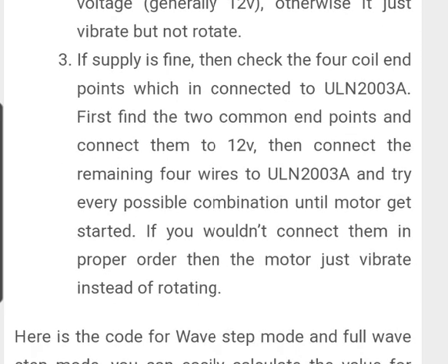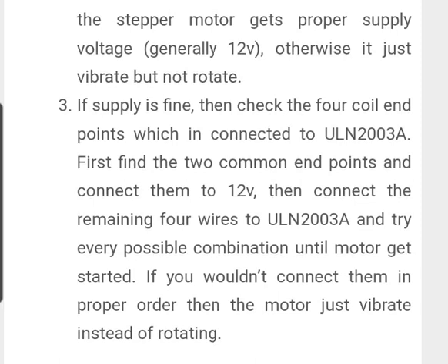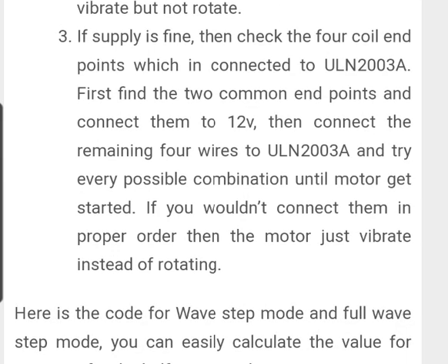Then if the supply is fine, we have to check the 4 coil endpoints which are connected to this ULN 2003A. First find the 2 common endpoints and connect them to the 12 volt, and then connect the remaining 4 points to the ULN 2003A, and try every possible combination until the motor starts. If we don't connect them in proper order, then the motor just vibrates instead of rotating.